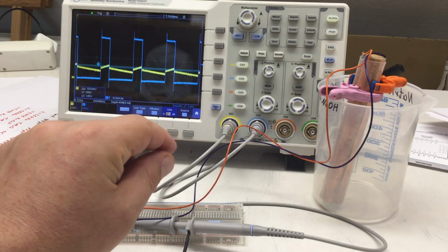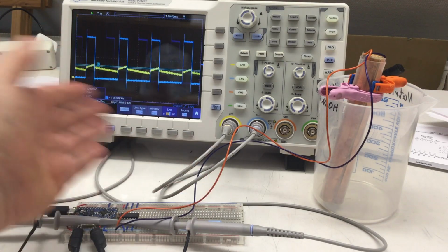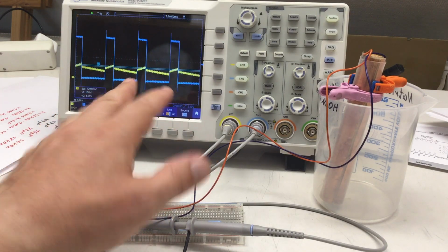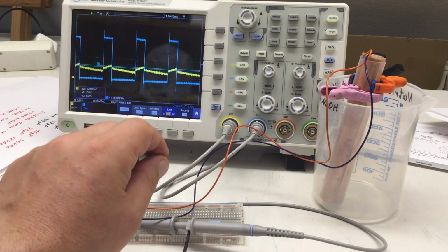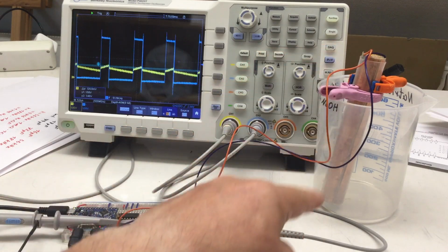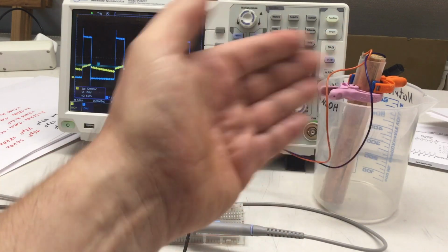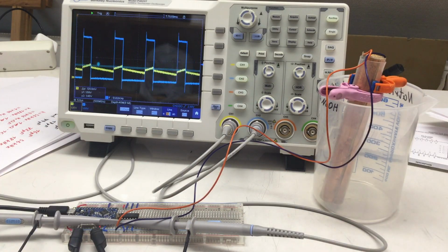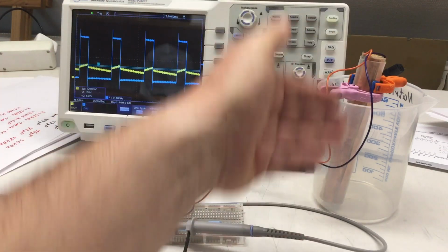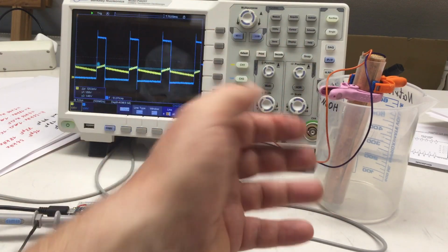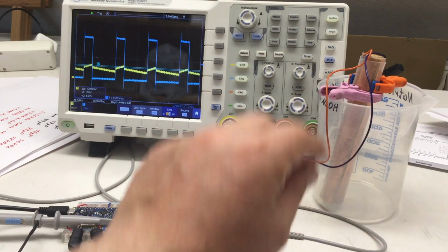There's another design aspect I want to talk about. We are now running with an almost dry sensor at 50 kilohertz. That's a little uncomfortably high for me frequency-wise. The reason being, if you look at that, that's a long metal rod. What does that remind you of? Yeah, an antenna. Given the transmit power we have here is probably not very high, maybe a few microwatts or a few dozen microwatts or so.